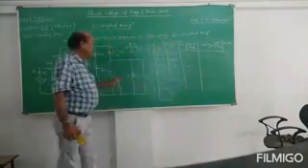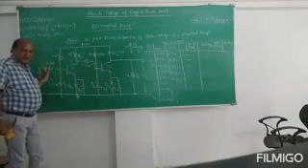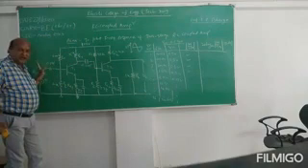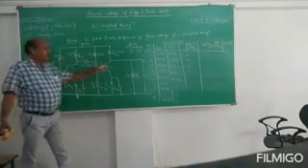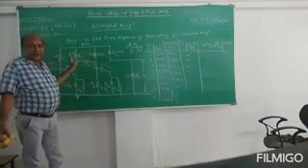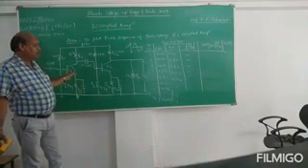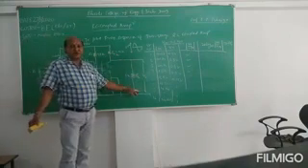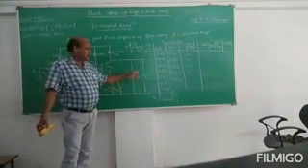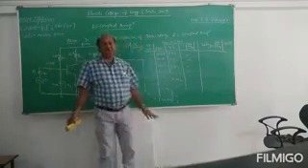Once you get this table up, connect this circuit properly. Connect the function generator at the input and one channel of the CRO at the input, connect the other channel of the CRO at the output. Fix the input value at 0.5 volt peak to peak and vary the frequency, and measure the output on the CRO. So you continuously check this output and prepare this table.